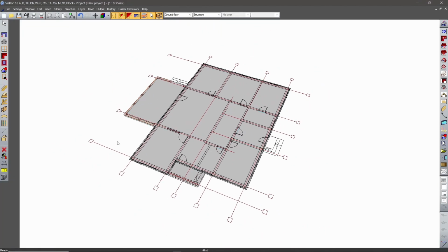As I can see, we can pair these two sides together, these two longer ones, and these two sides as well. We'll apply a dual pitch roof to one pair and a T-gable to the other. On the remaining sides, here and here, we'll keep the single pitch, and here we'll add a gable. So let's start with the dual pitch sections.